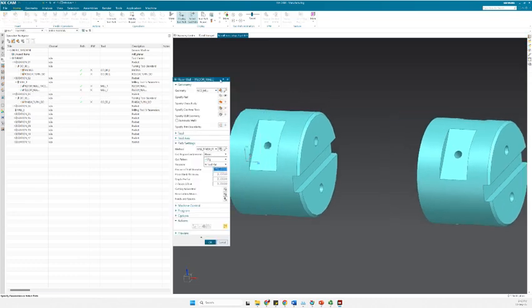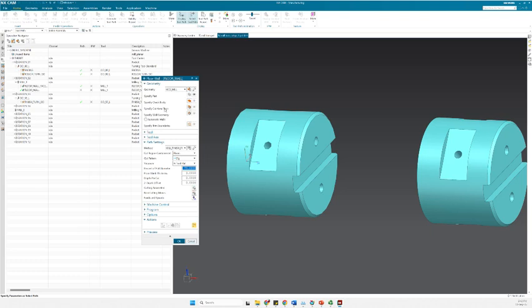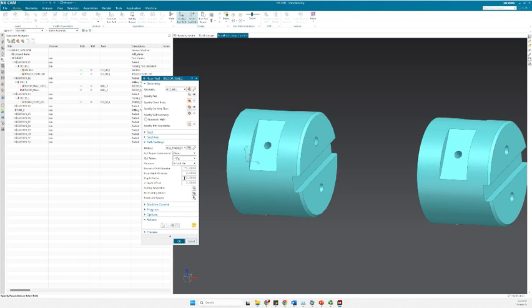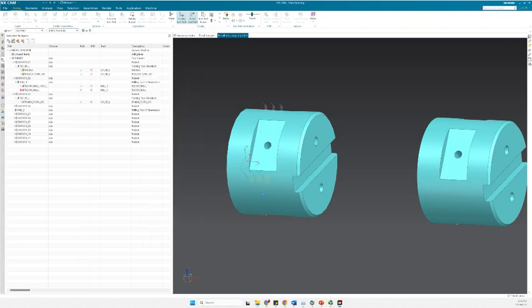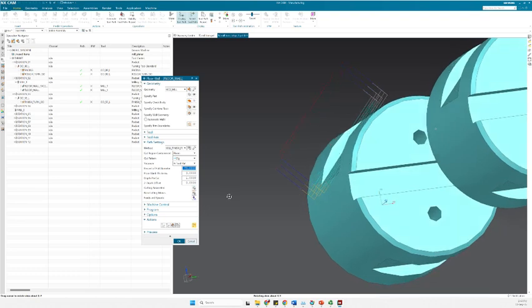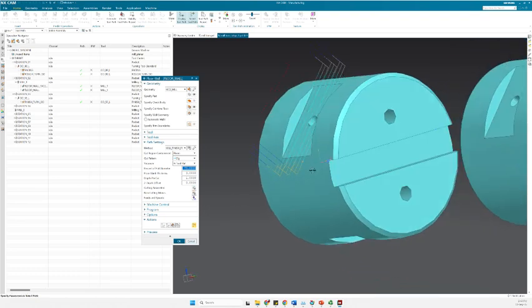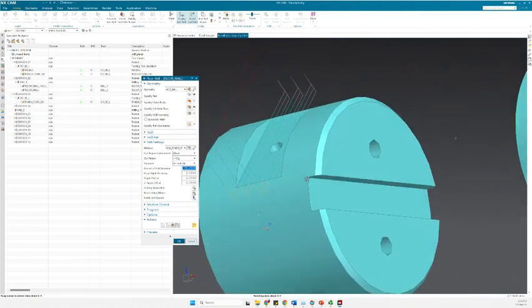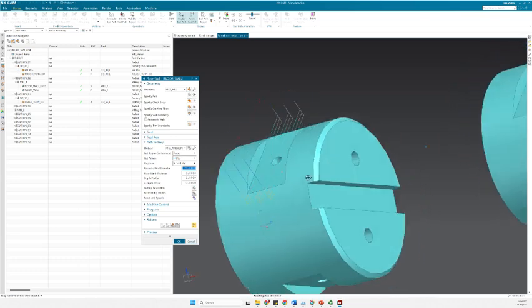So this is again the same. Now we have a different cutting area, specified cutting area floor. So this is the cutting area floor. And similarly, again, we can check the depth of cut is already 0. You can put the depth of cut. And then we can already generate and see what happens. It looks like that is already good because now the software detected that the tool needs to be perpendicular to this surface and it looks okay. But in some cases it wouldn't be perpendicular, and that would be a problem.